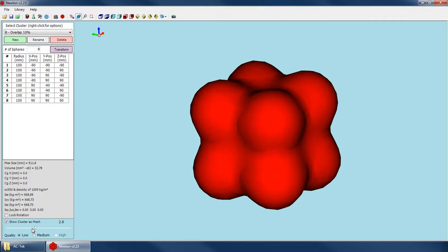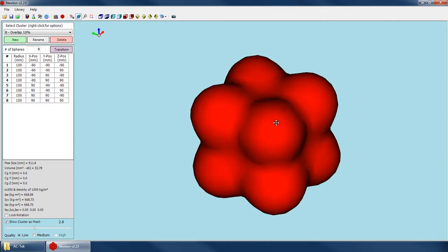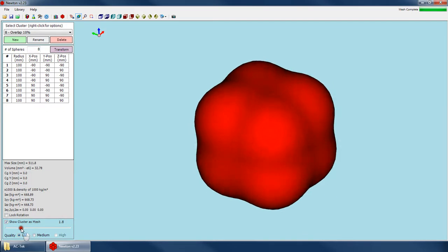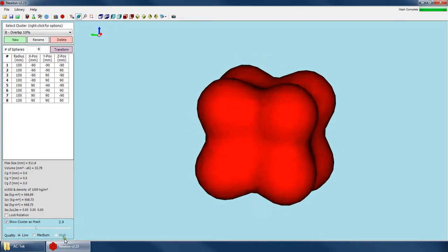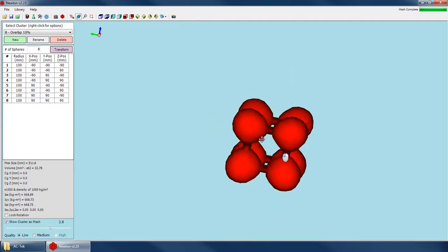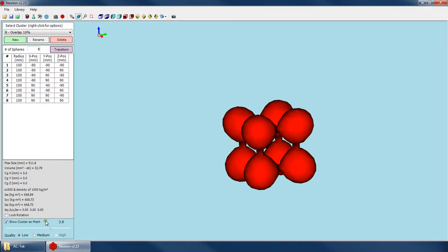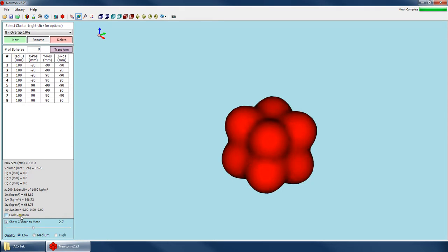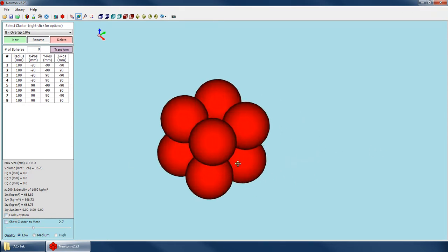But currently, when you run your simulation and open up the playback file, you can change the particle mode, the cluster mode, to meshed, but right now Newton is automatically calculating the mesh factor that should be used. We're going to change that so that you can actually say, well, I want to use my own mesh factor. Maybe I want it to look like this instead of whatever Newton gives me. So that'll be coming up in a future update. And I think that covers everything in this window regarding the cluster creation.